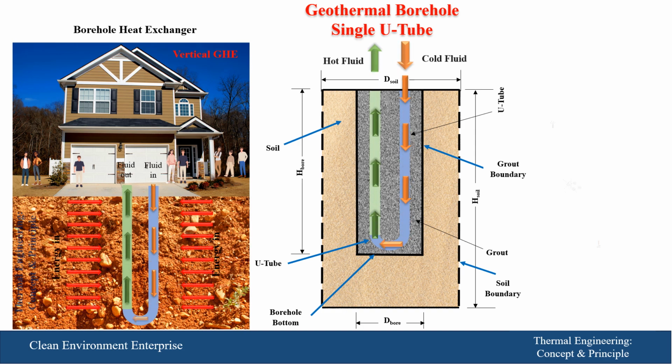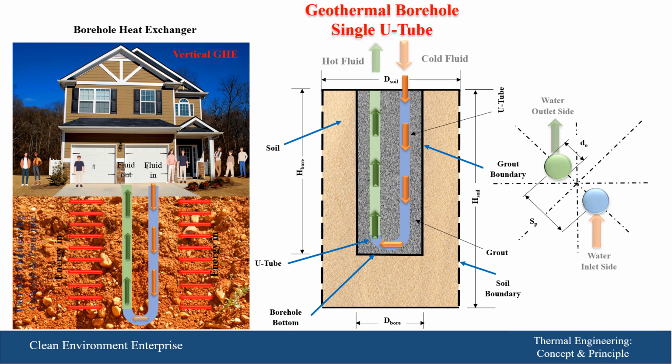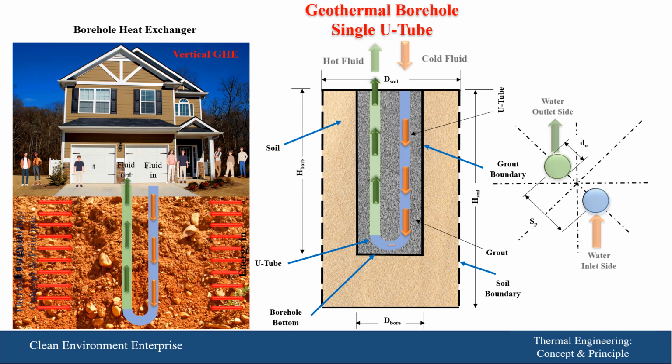So in that sense, we are extracting energy from the soil, which represents the earth structure, conducted to the grout, through the grout material, to the tube surface, all of that by conduction, and then by convection to the fluid which is passed inside that U-tube, and it could be water, shown in the right-hand side photo, water inlet and water outlet, water inlet representing the blue one, and the outlet is the green one.